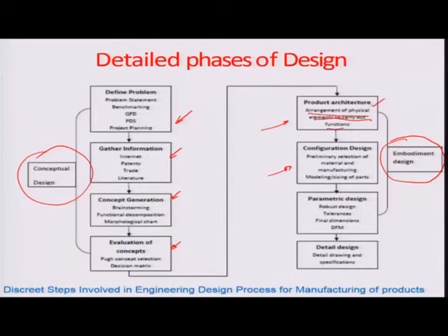So, it is a well-defined map to talk about the overall configuration of the architecture which has been planned in the last phase, and then finally fixing the different parametric aspects of the design and how to make those design aspects more robust, particularly by implementing the design in a process and getting an output from the process as feedback to control the design itself. And then finalizing the tolerances or dimensions related to the different aspects of the product architecture, and then finally design for manufacturability. So, all this comes into the real hardware part.